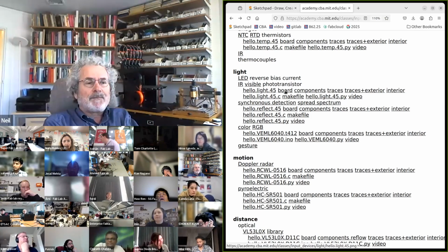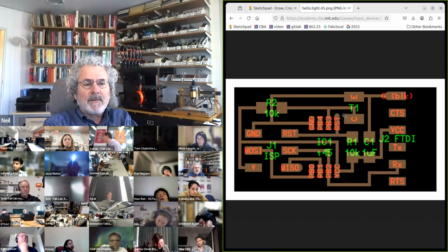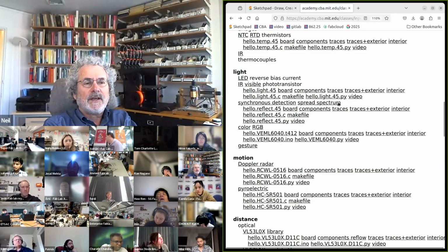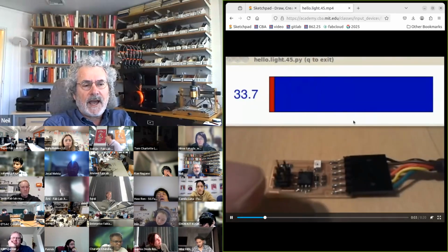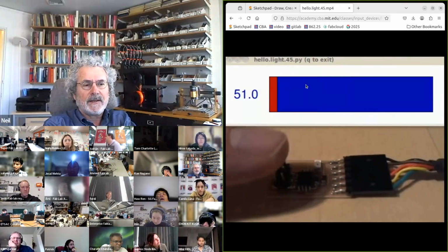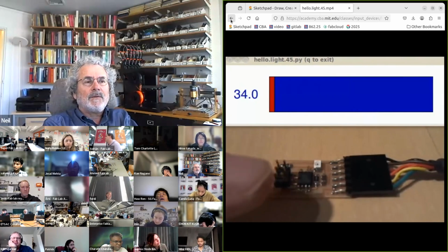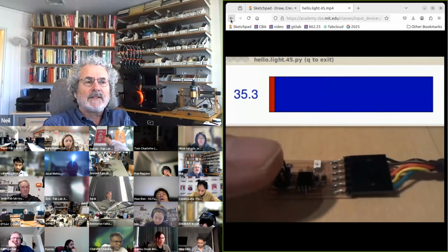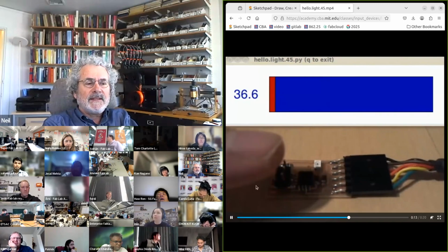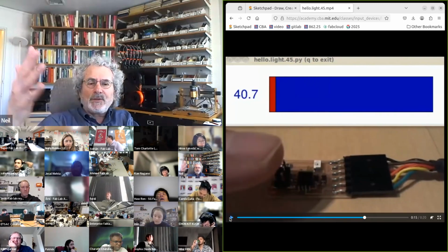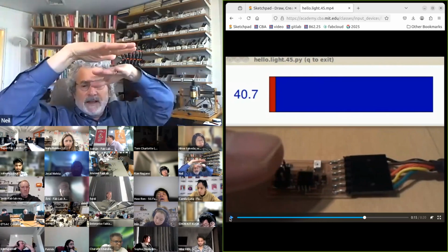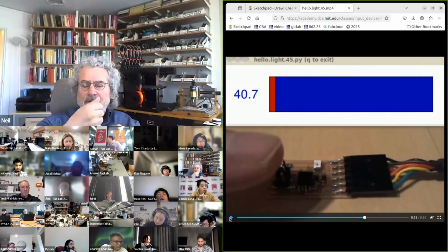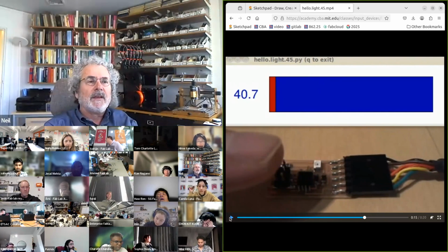So here I've got my phototransistor and I've got my resistor, and I'm going to measure a voltage. And so you can see the shadow as I come by. Now, there is a problem with that, which is that's sensing me, but it would also change if like there's sunlight and an airplane flies by or a cloud comes over or somebody turns on and off the room light.